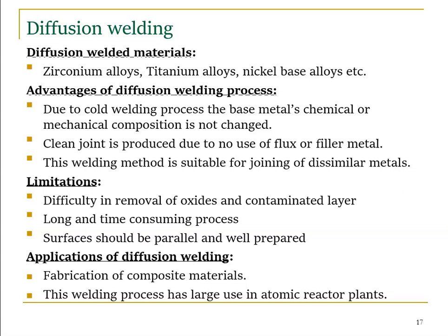Limitations are: it is difficult to remove oxides and contaminated layers, it is a long and time consuming process, and the surfaces should be parallel and well prepared. So these are some of the limitations. We need to prepare the surface, right? In the previous cases, like ultrasonic welding, there is no surface preparation, but here we need to prepare the surface before welding.